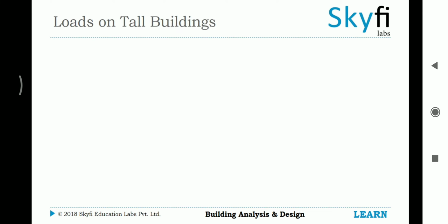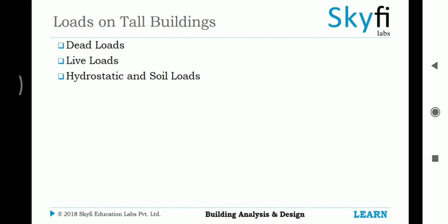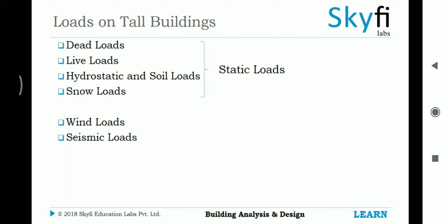Let's take a look at the common loads specific to tall buildings, which are usually considered during their analysis and design. They are dead loads, live loads, hydrostatic and soil loads, snow loads, wind loads, and earthquake loads. The dead, live, hydrostatic and soil loads, and the snow loads are considered as static loads, as they do not change over a period of time. The wind and the seismic loads are considered as dynamic loads, as they are not constant over a period of time, and keep on changing.